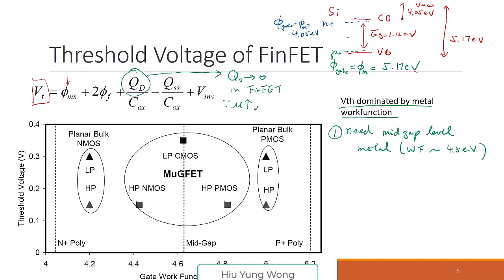I can also make the subthreshold look better, right? I also reduce band-to-band tunneling. But most importantly, it reduces the VTH variation. So I hope you can link to those. If not, go back to take a look.